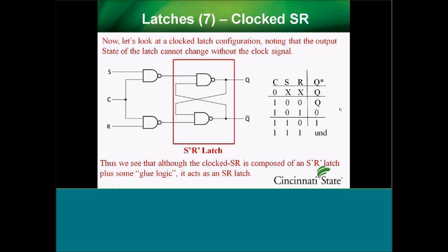Then when the clock goes high, you can start going through and looking at it. If you go through the analysis, what you find is that even though you're using the S prime R prime latch, the output looks exactly like the SR configuration of Q, 0, 1, and undefined. So we have this SR latch plus what I call glue logic, a couple extra gates thrown in, and this acts as an SR latch.